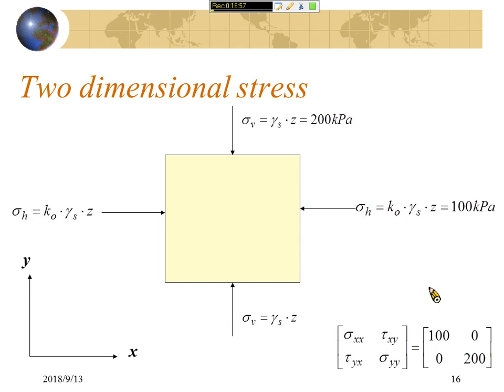If you have a tensor of rank 4, like the compliance tensor or the stiffness tensor, you will have 81 components for that tensor, and you cannot write it in a matrix form. For a tensor with rank 2, you still can express it via a matrix.